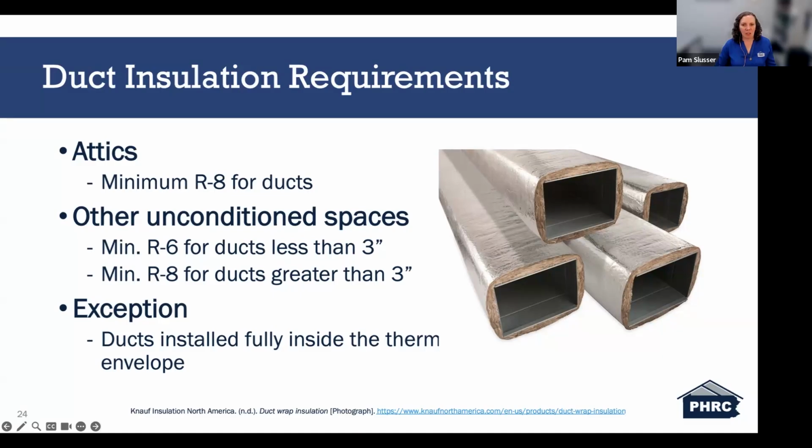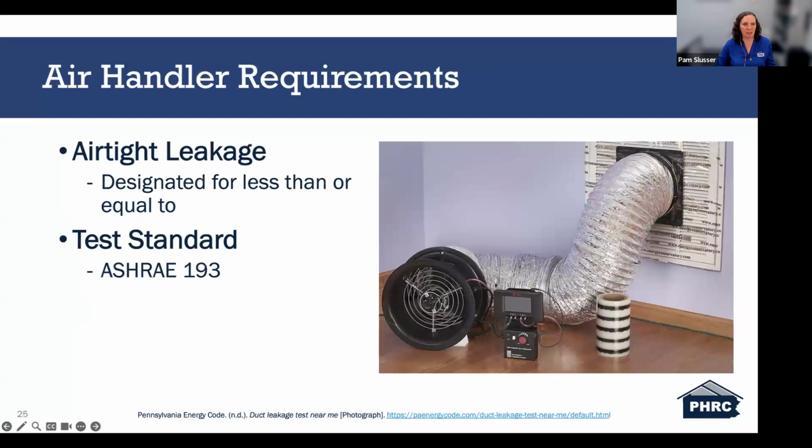However, there is an important exception to note. If ducts are located fully inside the thermal envelope, these insulation requirements may not apply. This reinforces the overall theme we've already discussed. Placing ducts inside the conditioned space can simplify compliance, and it can also improve the overall system performance of the HVAC system. So let's look at requirements related to air handler leakage and testing.